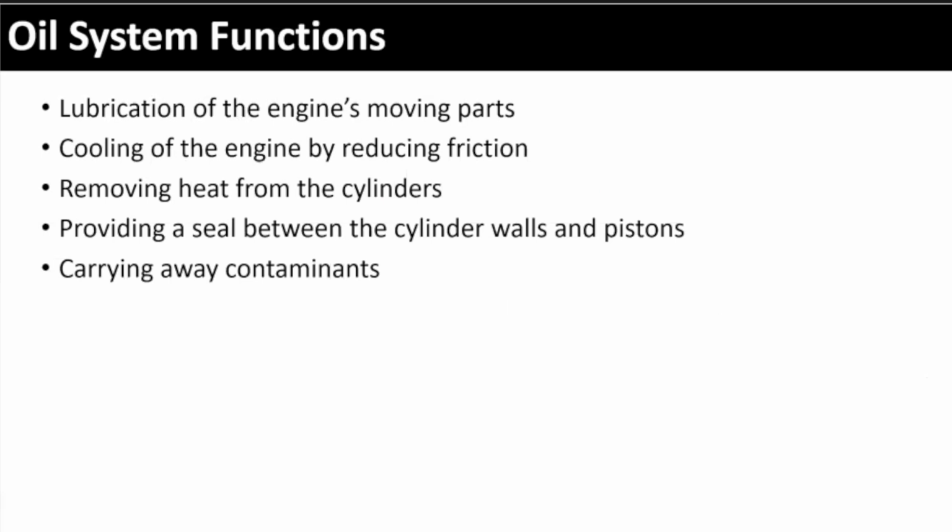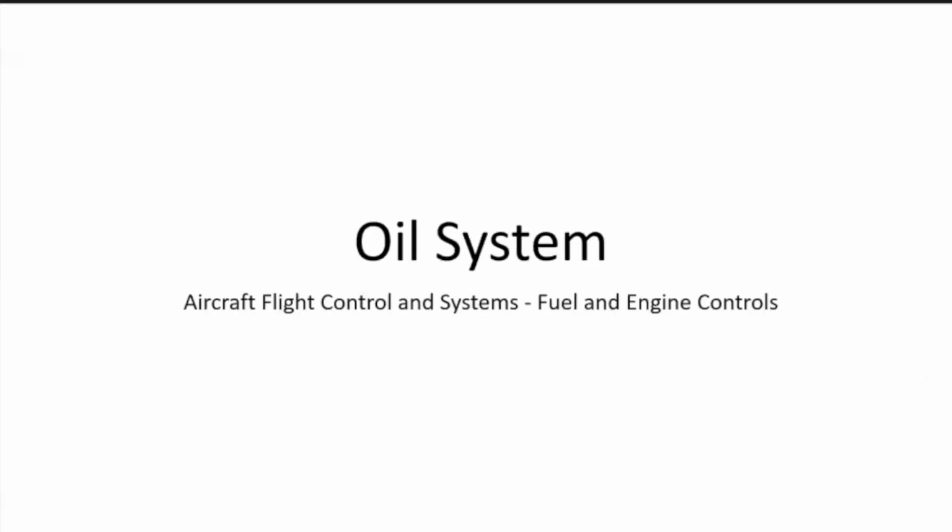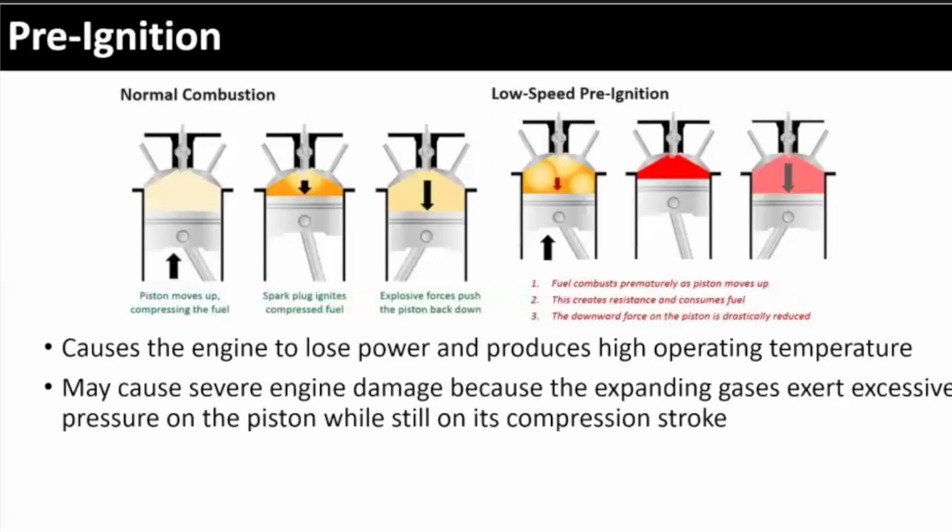All right, fuel. We talked about fuel. Any questions on fuel systems? Pretty simple stuff, right? A little bit more complex than cars, but still not bad. So how can you get that recognition? What are the causes? One of the biggest causes is just spark plugs, right? You've got faulty spark plugs or spark plugs that are gunked up.